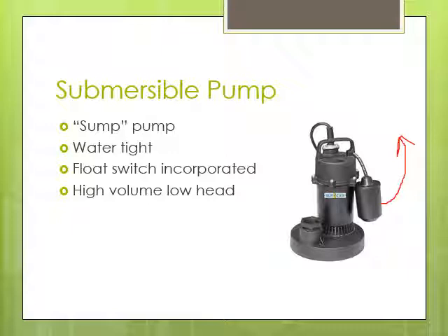If your greenhouse is in fairly flat land, like say Leamington, and you get a lot of rain, especially in the spring, that groundwater doesn't know boundaries, so it will seep into the greenhouse, and the ground underneath your ground cloth in the rows becomes wet. So they bury sump pumps, usually one per house, in barrels, and then those sump pumps pump the water up and out and into a drainage that goes to your irrigation pond.